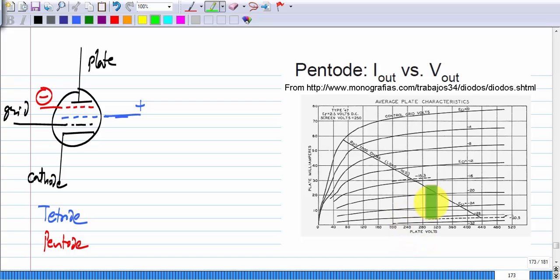Okay, so what is the difference between a MOS transistor and a pentode? Typically today when you talk about MOS transistors, there is of course a huge variety, but for most amplifier devices, the x-axis VDS will be a few volts at most, whereas here you can see that it's going all the way to 500 volts. Okay, but the principles are exactly the same. You choose some operating point here and bias your amplifier there so that you get a pretty high gain. Of course, you have to be a little more careful with building these circuits, because instead of 5 volts you have 500 volts, and you can't be sticking your finger everywhere in the circuit and getting an electric shock and so on. Okay, but the pentode is rather close to a MOS transistor, and this was a very popular amplifier device.